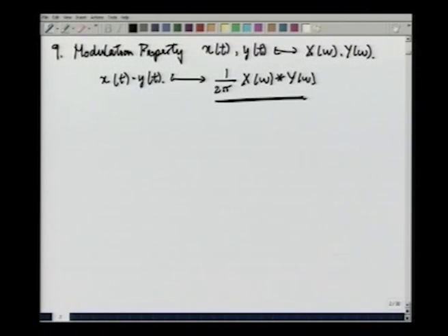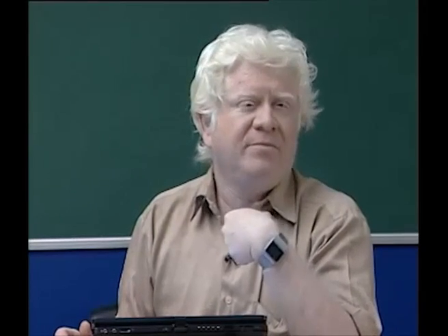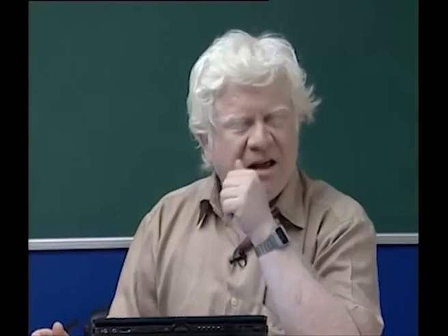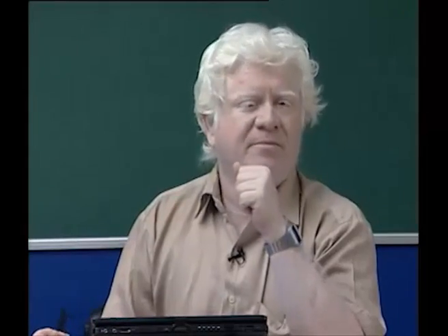All right, more properties. There is something called Parseval's relation. That establishes a relationship between the energy in x(t) and the energy in X(ω). They turn out to be proportional to each other with a scale factor of 1/2π that relates them.